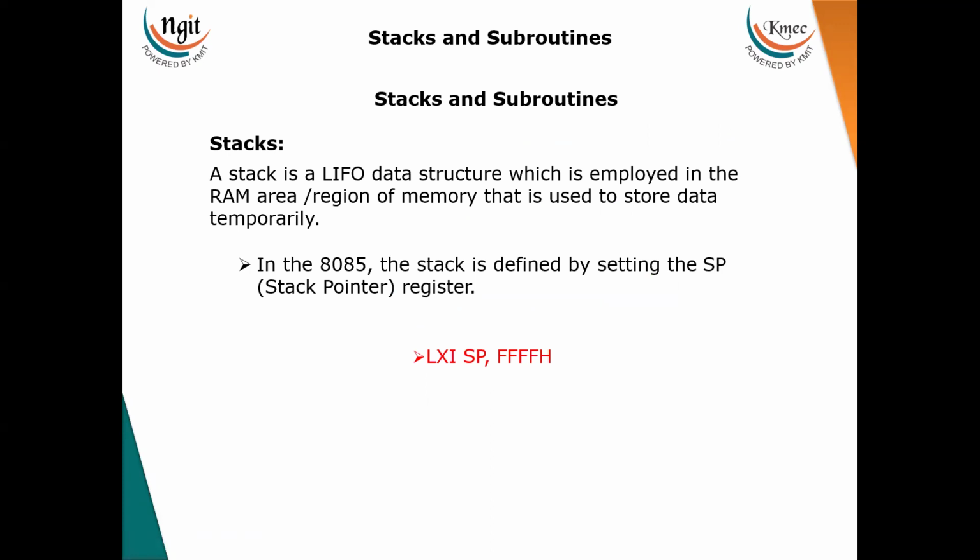Now this is unit 4, first topic, stacks and subroutines. Now what is stack? Stack is a LIFO data structure which is employed in a RAM memory that is used to store the temporary data. So now in 8085, stack is defined by setting the SP register.